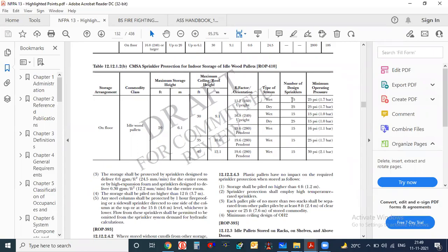Before, in the normal sprinkler, it was 9, I remember. We have taken 6, 7, 10 or 12. It was between 6 and 9, right? Yeah, between 6 and 9. Sometimes here it is 15. 15, 25: 25 for dry, 15 for wet. Whatever the numbers given here, this is the minimum value. Maximum you can take 1 or 2 sprinklers also, nothing will happen.